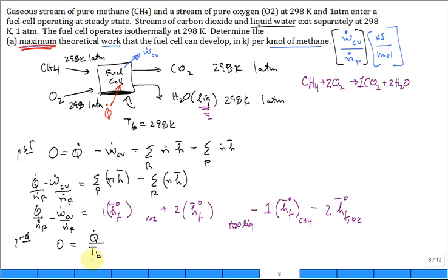That's a Q dot transfer in, right? The directions of both of these Q dots are consistent in the first law as well as in the second law, right? Then we're going to have N dot in with the reactants. So we're going to sum N dot S bar naught for each of those reactants, minus the sum of N dot S bar naught of each of the products, plus sigma dot.